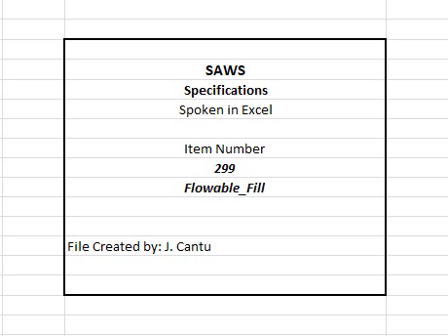Do not use portions which have developed initial set or which are not in place within 90 minutes after the initial water has been added. C. Do not mix flowable fill while the air temperature is at or below 35 degrees Fahrenheit without prior approval from the engineer. D. Monitor and control the fluid pressure during placement of flowable fill prior to set.